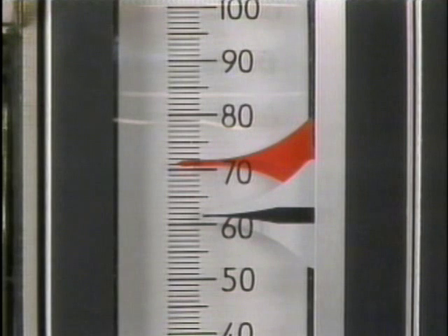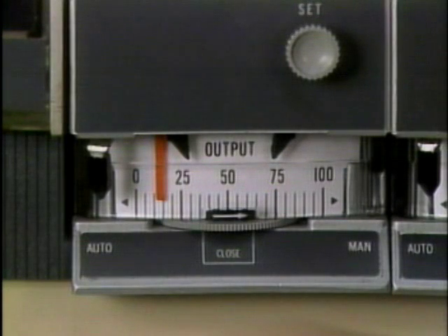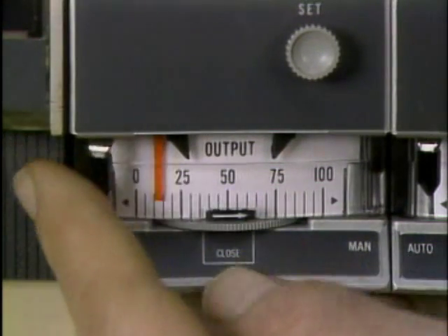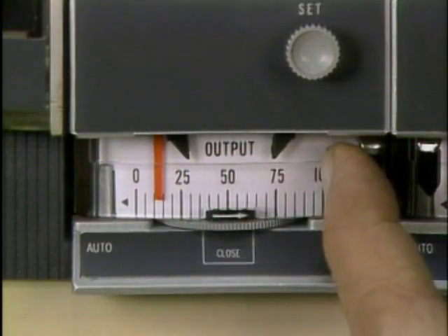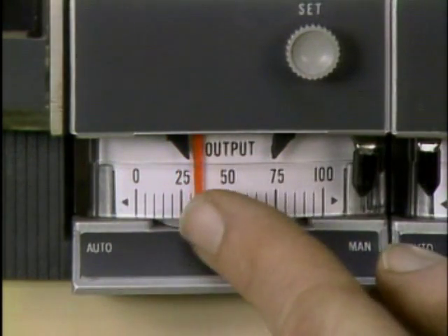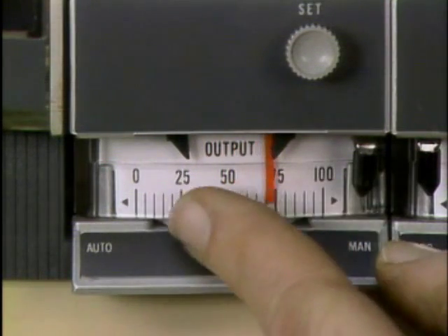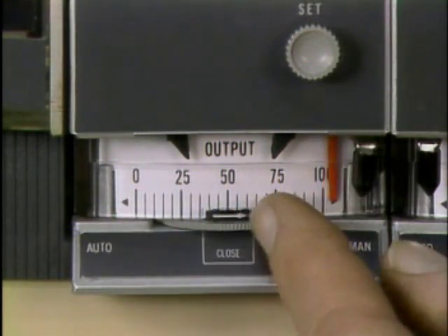In automatic control, the controller compares the signal it receives from the transmitter to set point and generates an output signal that maintains the value of the process variable at set point. The value of the process variable is indicated by the second pointer on the vertical scale. When a system is not operating in a normal mode, an operator may need to take direct manual control of a process variable. In manual control, the operator sets the controller output signal directly by using the thumb wheel to adjust the position of the final control element as indicated on the horizontal scale.